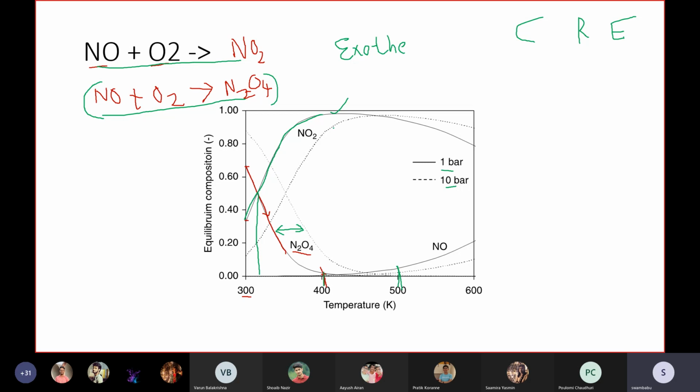So once you know this, you know what is required for the reactor: whether intermediate cooling is required or not, what metal thickness is required, whether corrosion is important or not. I am emphasizing all these factors so that once you know these basic details, you should be able to tell quickly that yes, I need this, I don't need this. Because of the time constraints, I cannot cover all the process industries. I'm covering important process industries and highlighting all the basic details so that if you take a new process industry, you should be able to easily understand these basic details by yourself. That is my aim.